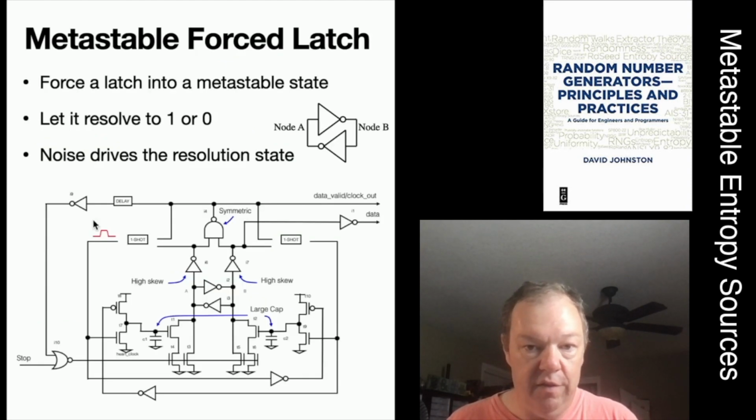So if we go back to this, we have these two buffers, and what they're seeing is a 0, 0 because we pull down both sides, and then we've released them and they start to move up. But they're still seeing a 0, 0 until one or the other diverges, at which point one of these will become a 1 and one of these will become a 0, or this will become a 0 and this will become a 1. And this buffer is labeled as high skew.